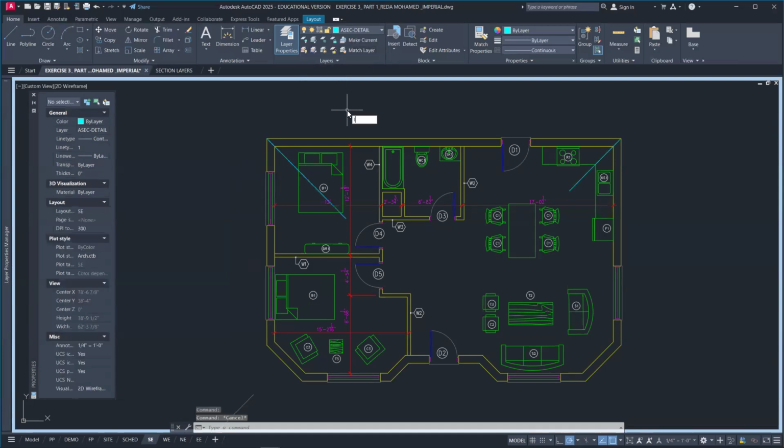And I'm going to create a line, which will be my section line. So I'm going to cut here, cutting through the bathtub, seeing the toilet, sink, cutting through this wall, seeing the door, the range, and cutting through the sink. Okay, so I think this is a good spot right here.